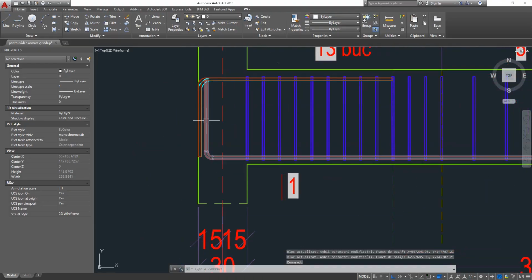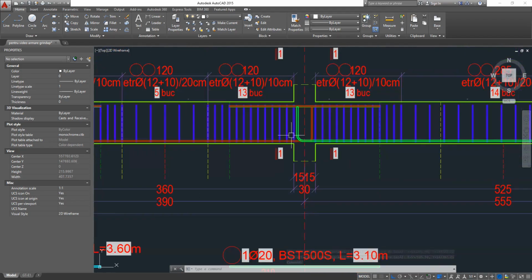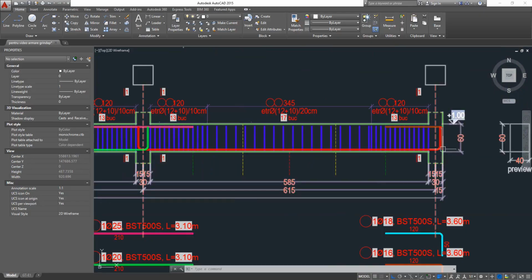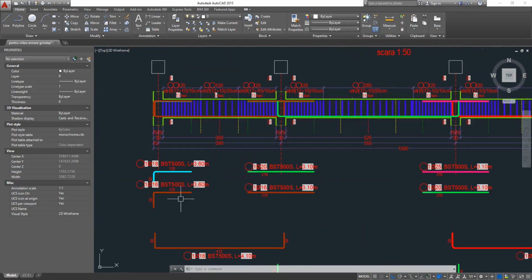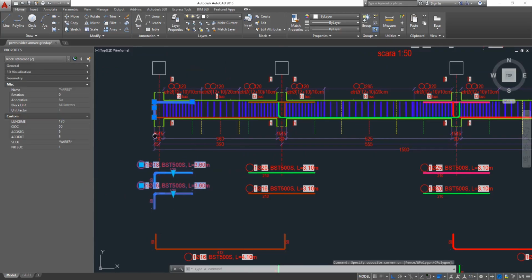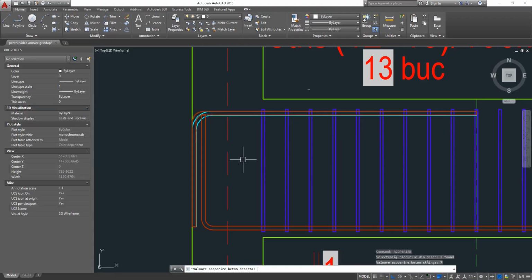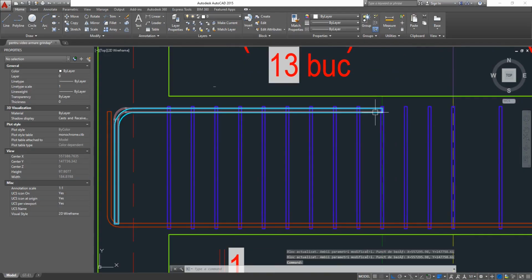Now, as you can see on each span, the bottom rebars are with a 4 centimeters coverage, and we wish the same for at least the first rebars from the left. We're going to use a concrete coverage of 7 centimeters to the left and 0 to the right, meaning we're going to let it for the time being as it is.